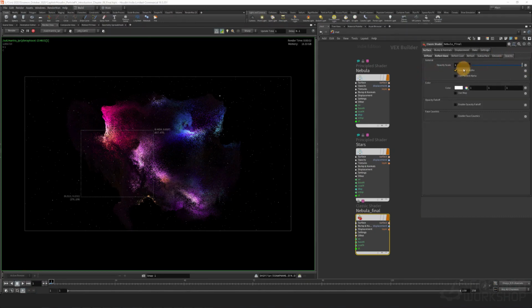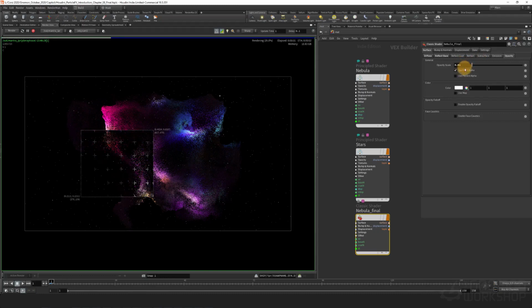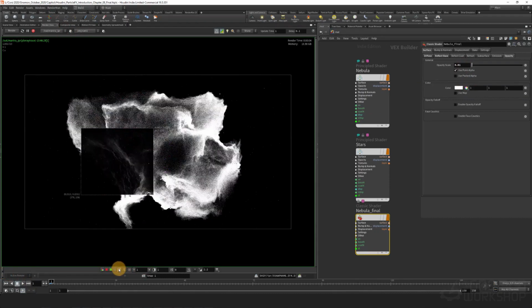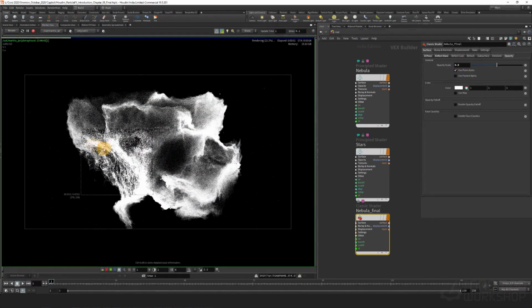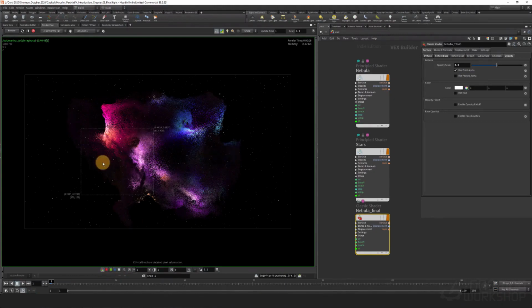With opacity we can have a really nice rendering technique because it will simulate something similar to the Krakatoa rendering engine. You know, it was a plugin for 3ds Max and Maya. So let's go for example for 0.01. That's really low. You see that if we go to see the alpha channel also, that's the alpha channel actually. So let's try with 0.5. It will be more visible than before. Let's go back to RGB.